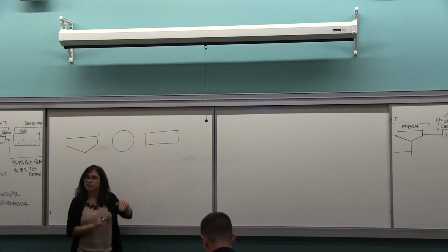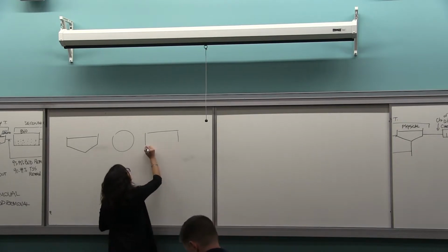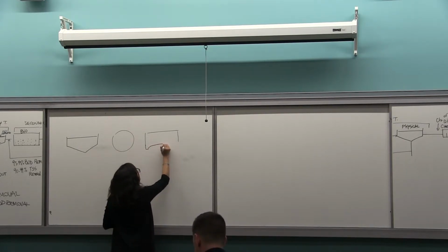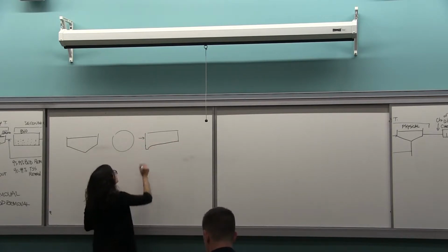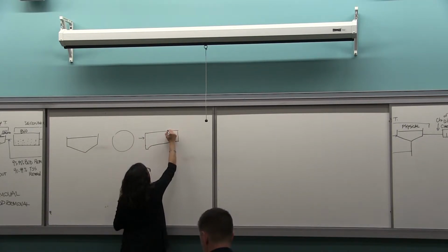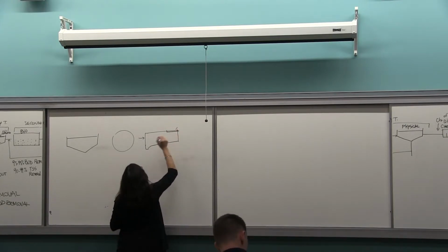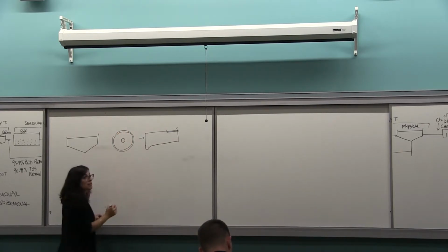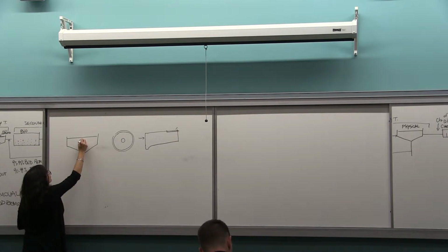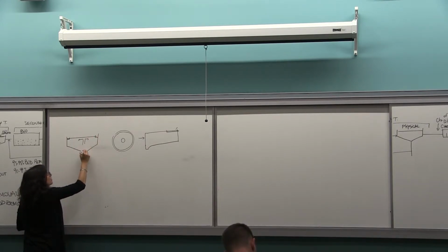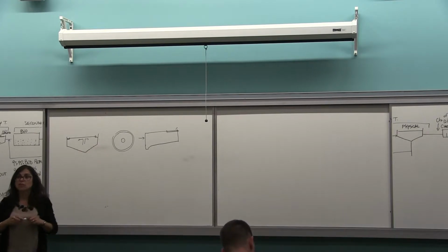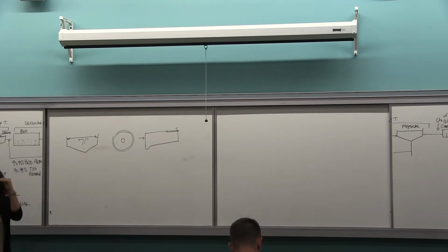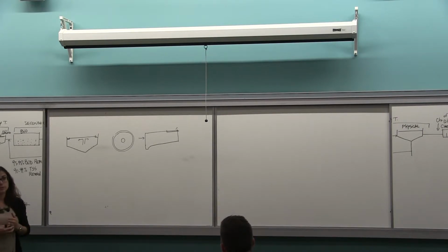Again, it's not straight at the bottom, it's actually like this. Water comes this way and leaves from the weir on top, and here it leaves usually on the side. Enter from the middle, distribute it, and then the water exits on the top, and the solids are collected at the bottom. So it's just a physical separation to settle heavy, settleable solids, right?